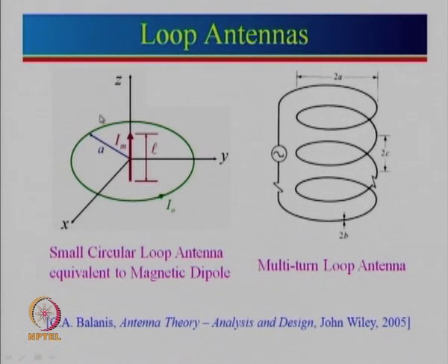So, if we assume that the current is uniform over here, then this can be thought in a slightly different way. See, when we were looking at a dipole antenna, so we had a vertical dipole antenna, and where was the magnetic field? Magnetic field is around the dipole. So, if this is the dipole antenna, magnetic field will be like this here. So, that is what is known as omnidirectional, and then the E field is like this, which was making a figure of 8. Okay. So, that is a directional antenna.